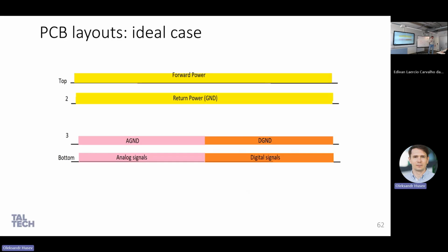What is the space? Where is the space? I'm interested in this distance and this. Between layers. 0.2 millimeters. Yes, 1.2 millimeters between these two internal layers, right? And here, okay, it's around 0.2. You can calculate if you have a total of 1.6, right?